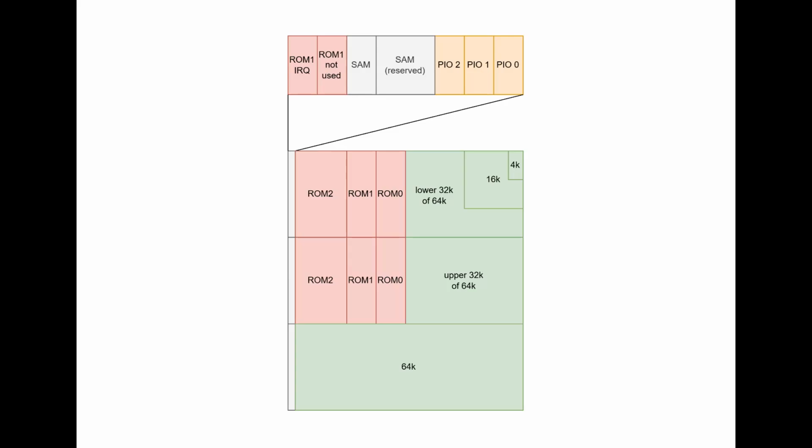The address space can be all RAM, so 64K, less the PIO and SAM addresses, which add up to 256 bytes, 50/50 RAM-ROM, 32K with a RAM in the lower half, with a paged RAM toggle where the upper 32K out of 64K RAM is remapped into the lower 32K.